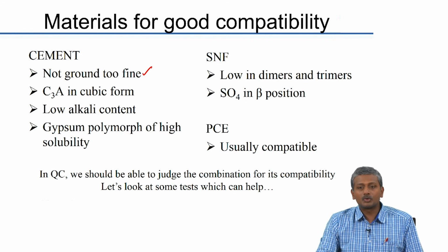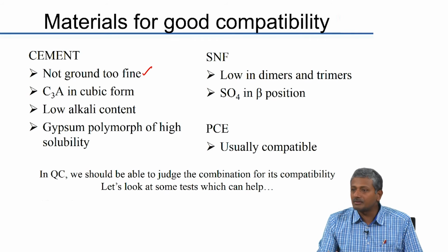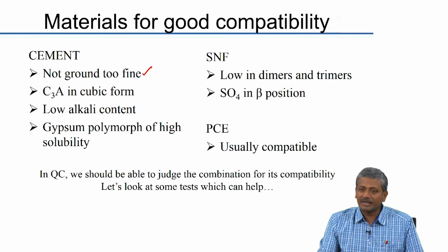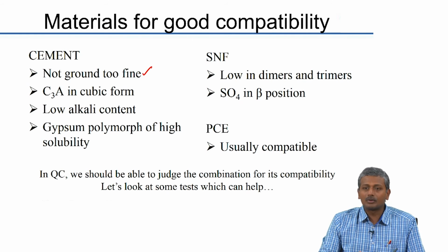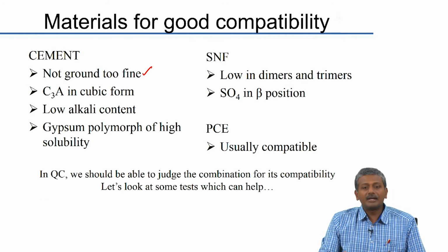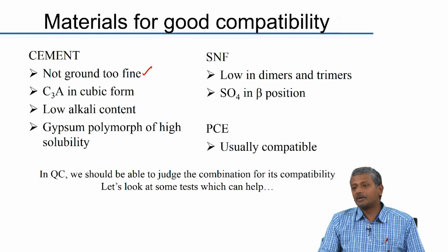For example, I showed you those EN cements, right, which have 2 day strength requirement. In those cases you have to grind cement fine, you have no other way out of that. Okay. So, when you have the chance to grind cement finer or coarser, not grinding too fine may help in reducing the compatibility problems.